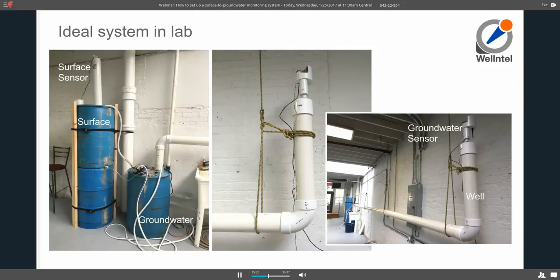So on the right-hand side of this left-hand picture, the lower tank on the right is representative of our groundwater condition. It is simply an open tank. It isn't truly groundwater, right? It's a directly coupled system where the surface water drains to the groundwater. There is no sand here, so it's not slowed by a percolating effect. The only way we can slow this, frankly, is to reduce the diameter of the valve, and we can do that. You can see in this image a pump atop the groundwater tank, and what we'll be doing momentarily is pumping up into the surface water tank.